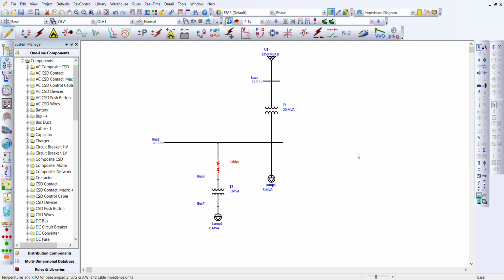Yeah, copper 5.0. Okay, this is one. Now remember, from the specifications, it's supposed to be NEC EPR 133%. Now the percent phase should be 133, this, and this is 100, so we keep going down until we get to 133. Yeah, we've gotten to 133. So now we've gotten frequency, check, 60 Hertz, the type, copper, correct, the kV, 5.0, correct, percent phase, 133, correct.